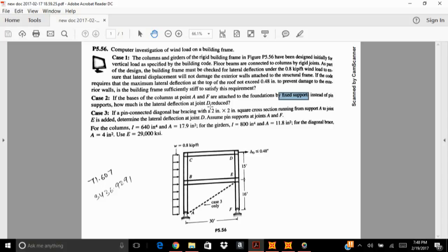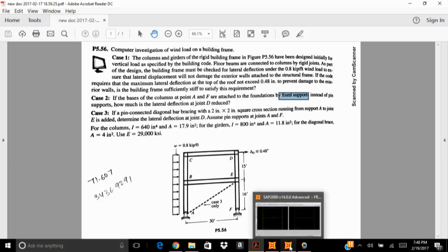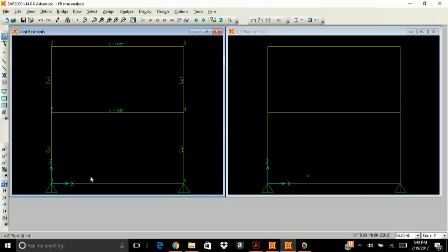They will just take tension. They won't even take compression. It will act like a truss member, because it won't take any moment or shear. So the thing is, while making this brace element, I have to consider it as pin joint at both ends.